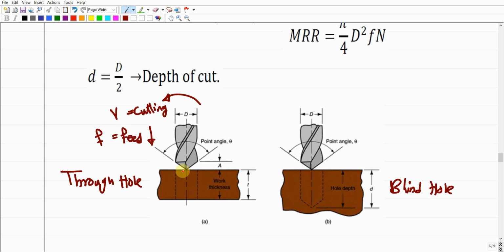So for example, to open a through hole, and this is something you should understand here, the twisted drill is going to start from the beginning, from this point here. So it will continue going down, going down, going down. One would think that this point will be moved here, right, up to this point. If we did so, the twisted drill will be here, and because of this triangular tip, this part will not be removed and this part will not be removed. Both will not be removed.